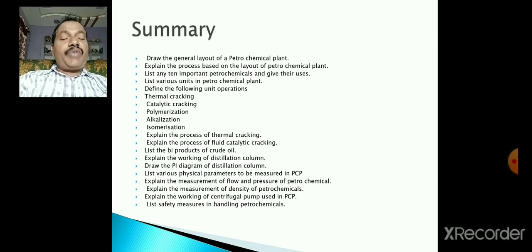The vortex street waves apply pressure on the piezoelectric transducer, which gives us, for each strike of a vortex wave, a voltage pulse, and the frequency at which this voltage pulse is produced is the frequency of the vortex street. So that frequency is found.